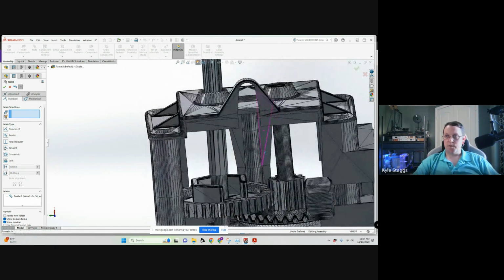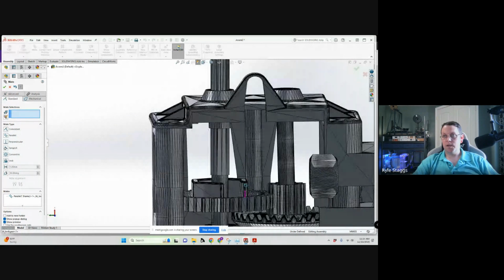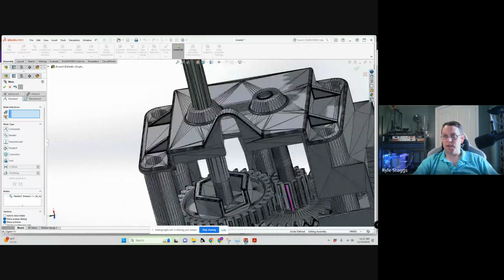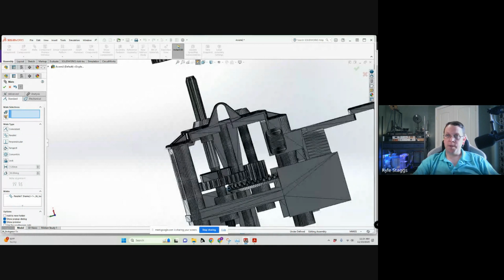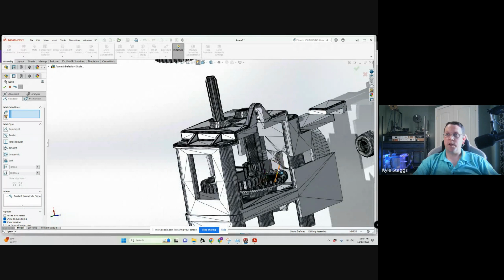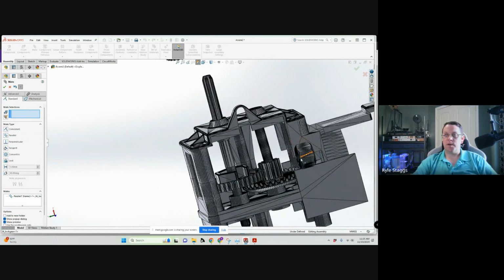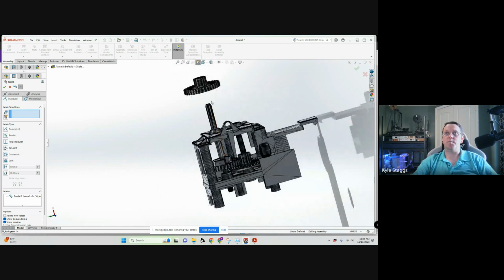Okay, so for instance, you can do the lock gear here, and it'll drive and mesh rather nicely with this gear, leaving room for the crown gear. But you've got a lot of tight clearance here, but you'll have engagement with the spur gear here, rotates this gear on an idler. Then you have the lock nut that goes on here, locks this to the shaft, and now this becomes your drive axle. And instead of the gear out here, you'd have your wheel out here somewhere.